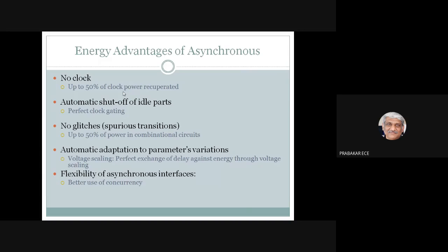If you have experience in FPGA designs, sometimes you might have experienced all these things, right? It will not show up for simple cases. You have to implement some complicated programs which consume some 20,000 or 30,000 logic elements. In that case, after some working time, the same system with the same clock frequency may not work. This may be because the FPGA gets heated up, and because of this heat there is a change in the delay, and the same clock may not work for that delay. So you have to reduce the clock frequency so that your system will work.